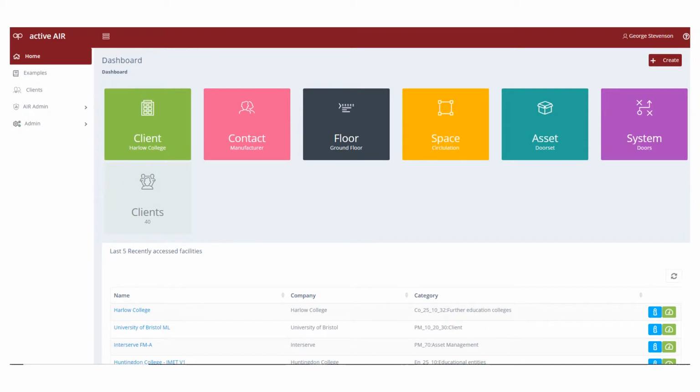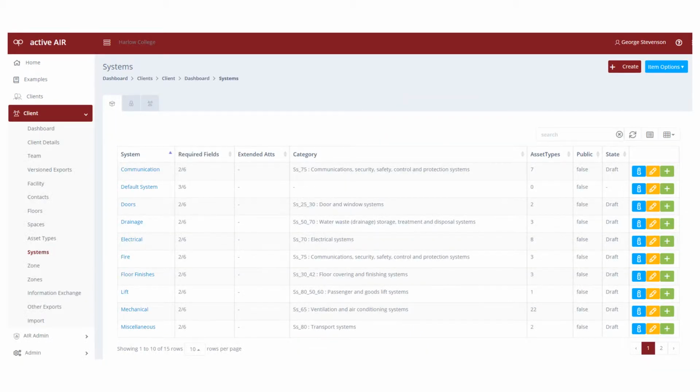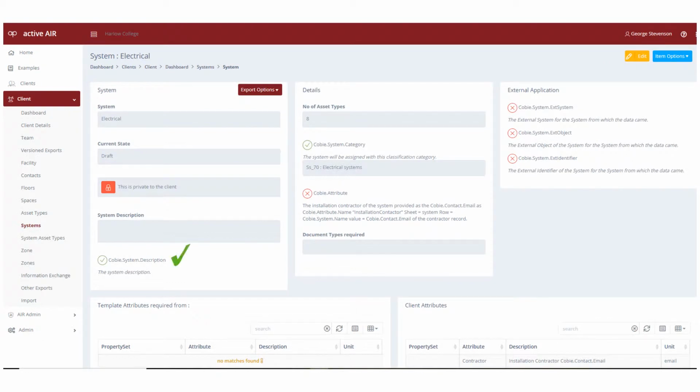For example, the designers are required to provide floor and space numbers, types of spaces, finished ceiling heights, and net areas of each space. A library of the types of systems that might be used in that type of building defines the basic information they need to know about a system. In this case, they ask for a system description, the Uniclass category, and the contact details of the installation contractor. This set of requirements is saved in the library and can be used on all their other projects.